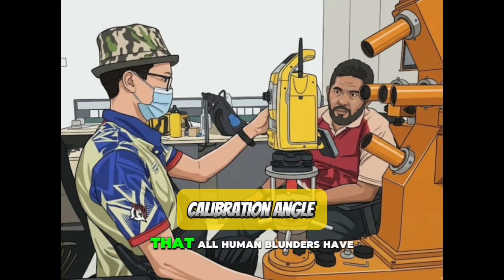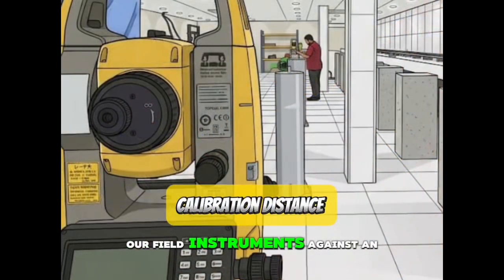Handling systematic errors via calibration. Once we are confident that all human blunders have been eradicated and our field data is clean of gross mistakes, we are left confronting the more subtle, built-in flaws of our equipment, known as systematic errors, which we fortunately handle through calibration. Because systematic errors are consistent and predictable, meaning the total station or GNSS receiver is consistently reading too high or too low due to a manufacturing defect or physical wear, they follow predictable physical and mathematical laws. This predictability allows us to fix them by comparing our field instruments against an absolute, trusted baseline standard.